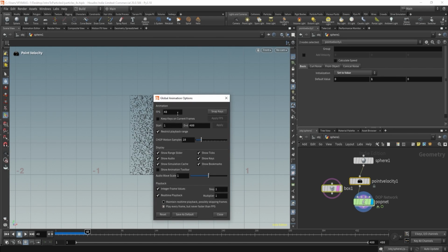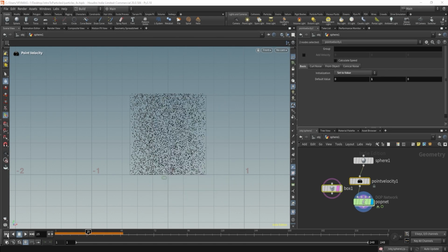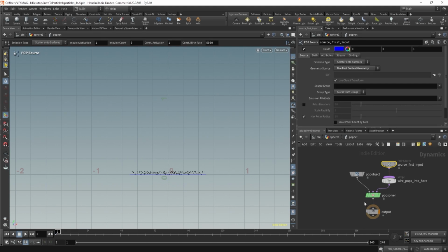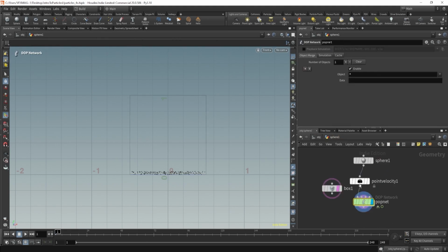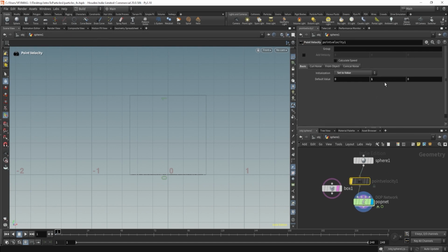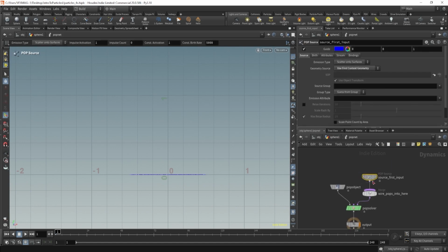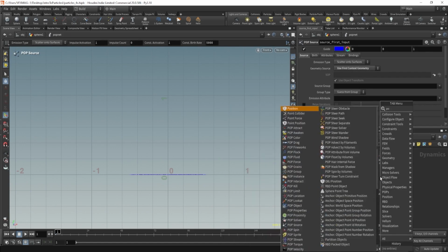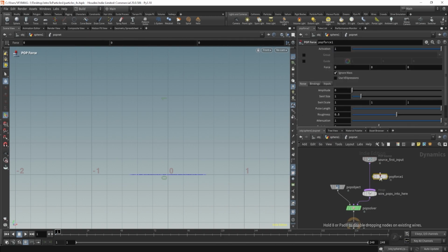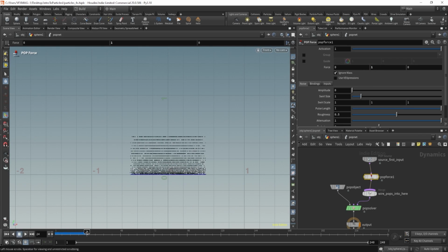So let's reset everything, this as well. We understand velocity, but how do forces work here? Is it the same as velocity? Let's just check that as well. So here I have mentioned 1, right? So I'll just disable this. I'll just check force. And this is just for position only, so don't worry about all those things. I will cover them later. So let me type 1 over here. So it should reach here on frame 24, but it's not.